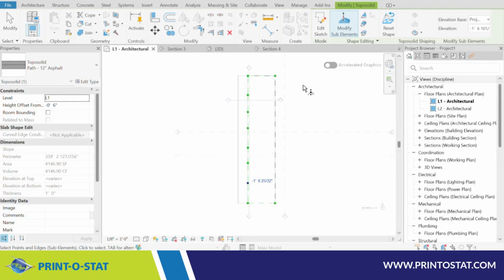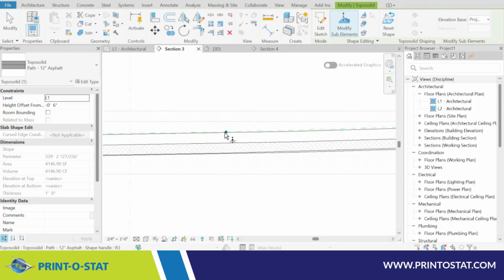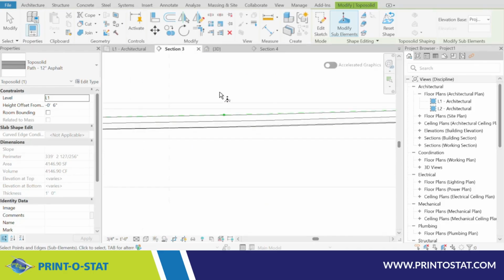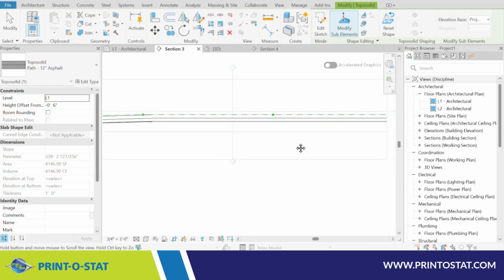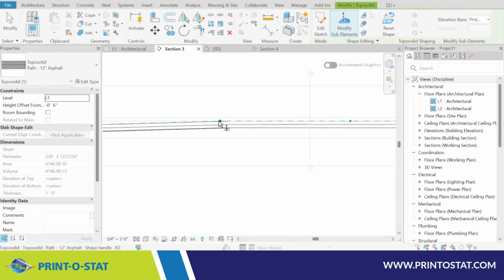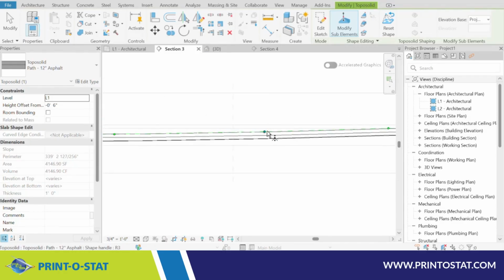What I did was, I was in the middle of doing this. I had the point cloud on. I had some curbing and sidewalk in, and I wanted to match the existing. So I knew, based on the point cloud, where the actual grade was, because I was going to do existing and new. So I created a section that was looking at these topo points. That's this section here. See how the topo point is there at the top of the topo. There's the first couple. They're at 6 inches. The next one was at a foot, right?